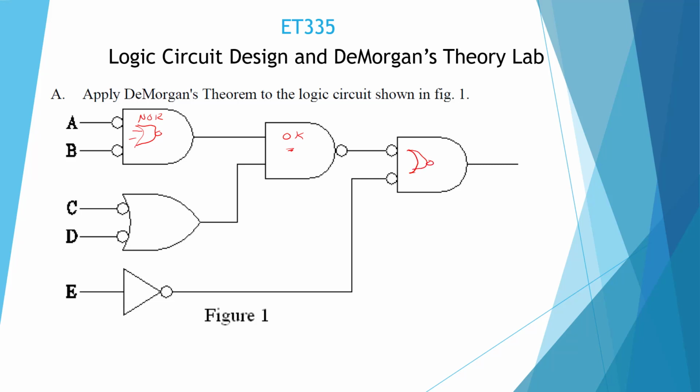This inverter's fine. Don't cancel these out, otherwise we're not going to be able to do that. So we're going to have this inverter into our OR. And this guy, again, let's DeMorganize. Let's change the symbol, push the bubbles, so we have a NAND. Those are all available in our kits and in Multisim. So we're going to build this DeMorganized circuit in Multisim and see what the output would be.